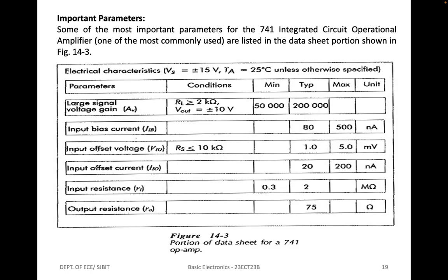The DC supply voltage for electronic circuits can vary when the supply current changes, and in some cases there is an AC ripple voltage superimposed on the DC. The supply voltage changes can be passed to the output of an amplifier. Ideally, the supply voltage variations should have no effect on the circuit output, but how good the amplifier is at attenuating supply voltage variations is determined by the power supply voltage rejection ratio, also called PSRR. This is usually specified in decibel form.